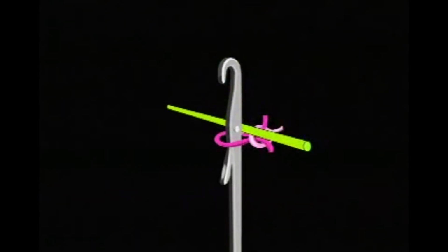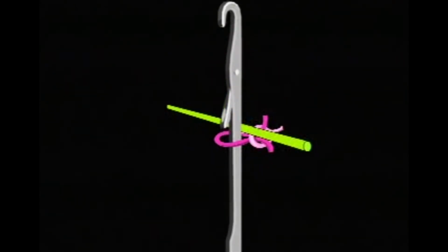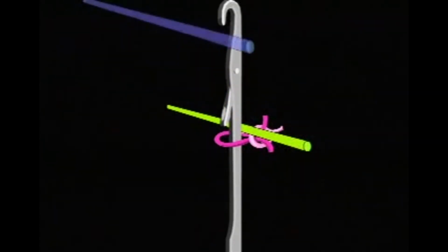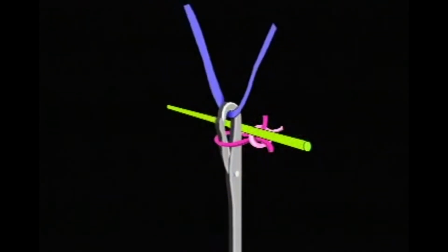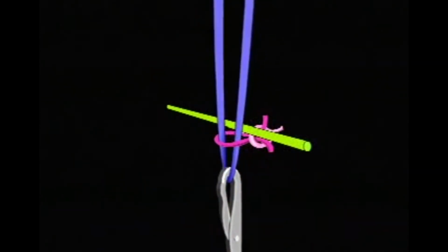To produce the float stitch, on feed 1, a yarn is laid to rest behind the hook of the needle. The needle remains at the rest position. It is not activated in the float cycle. In the knit cycle, it is. When a subsequent yarn is knit at the next feed, the missed yarn floats to the technical back of the fabric.